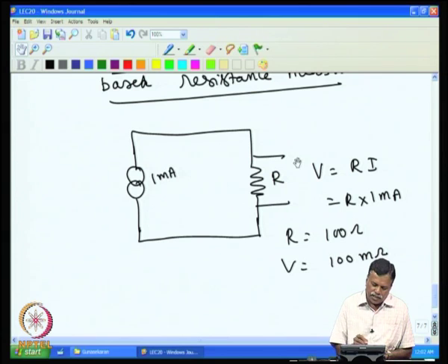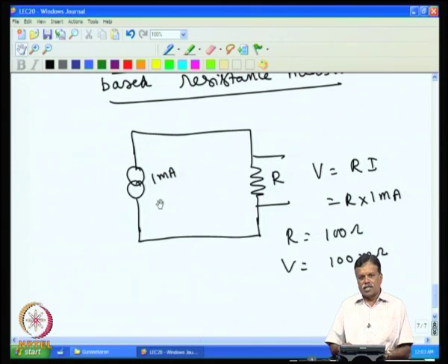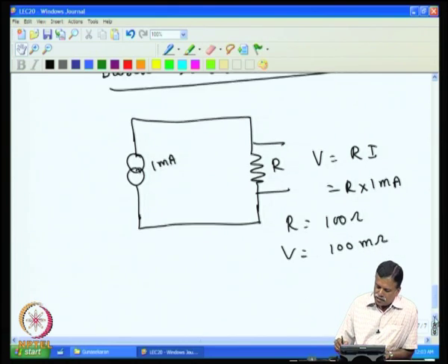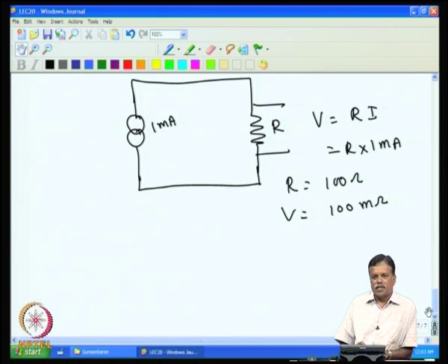Now, we depend upon this current source to get this voltage, but we have to obtain this current source using a circuitry, and that current which we had fixed at 1 milliampere may not be 1 milliampere at all room temperatures, because the main problem in electronic circuit design is room temperature variation, because it can make the circuit performance deteriorate. It can deviate from our design values. For example, I designed the circuit for 1 milliampere current, the current should always be 1 milliampere, but the current will not be 1 milliampere at different temperatures. Maybe at room temperature I would adjust it for 1 milliampere. When temperature goes up, this current may go up or come down,